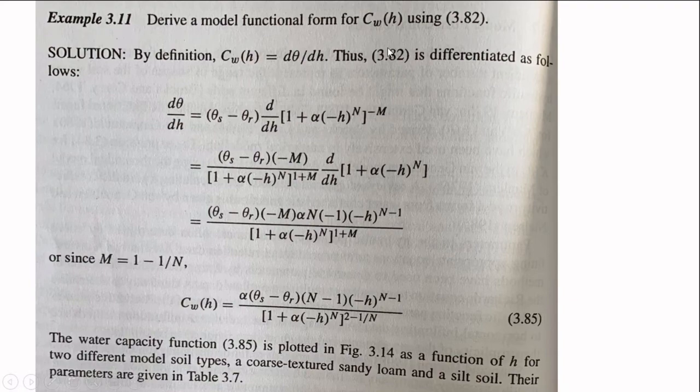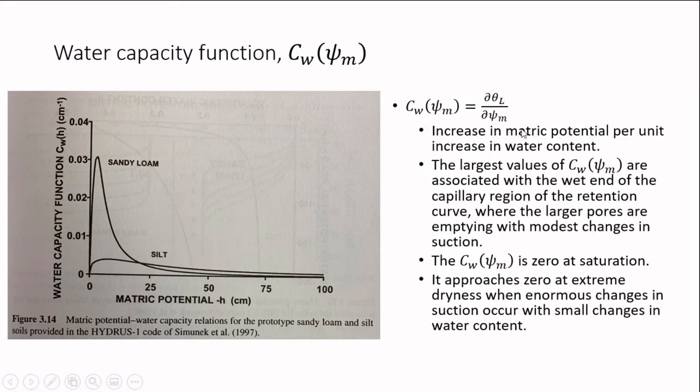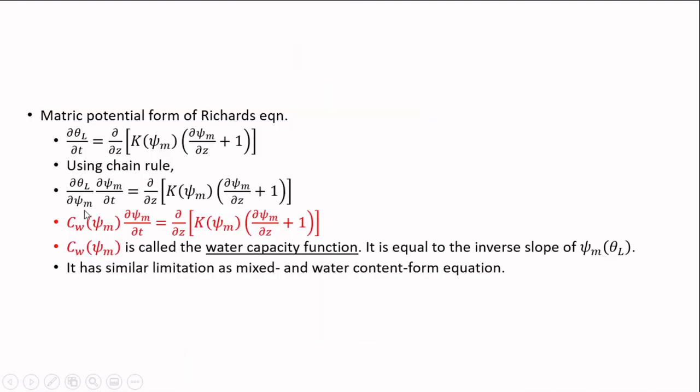All right. So this equation is also referring to this one, and this form is used here. If you want to use the Richards equation, you see that there are different variables, for example these variables: the relation between the derivative of volumetric water content with respect to matric suction. So this relationship has to be determined. You must derive the mathematical equation for this part before you can even solve this equation.